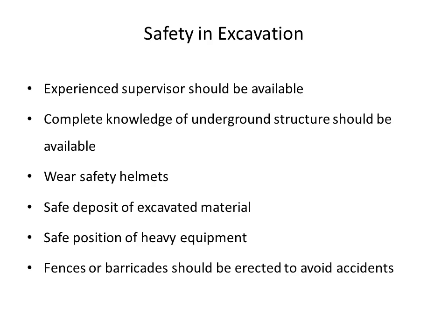And the next one is safe deposit of excavated material. We have already said that the excavated material should be deposited away from the trench. Then comes the sheathing. That is, we are excavating a trench and there might be some chance of the sides of the slopes falling down. So this should be avoided by providing proper sheets on the side of the trench.